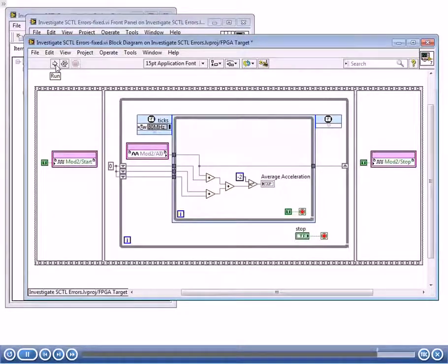We saw that there was a total delay, I think, of about 9 nanoseconds. So if you do 1 divided by 9 nanoseconds to figure out what your maximum frequency that will compile at, 80 megahertz is well below that. So this should compile. So I'm not going to take the time to compile it here, and you can just take my word for it, or you can do the exercise.